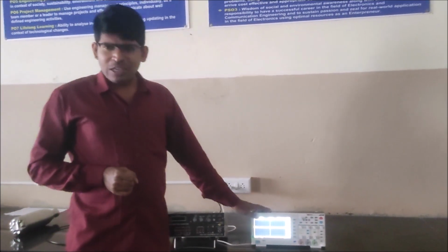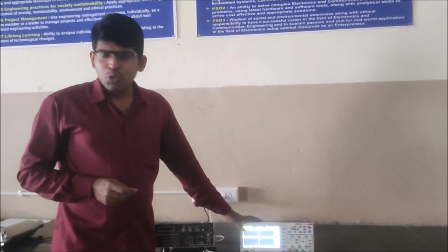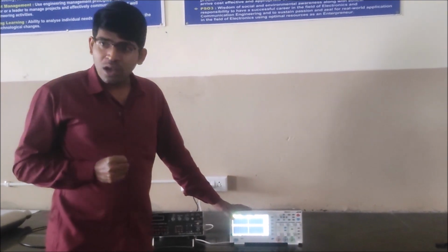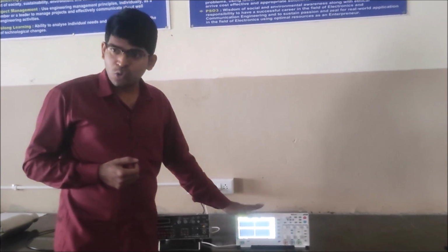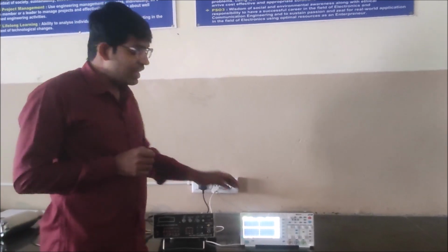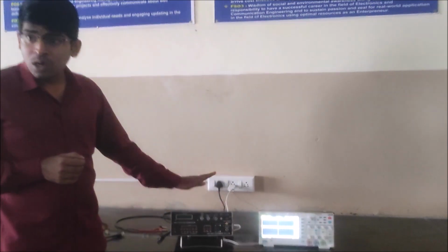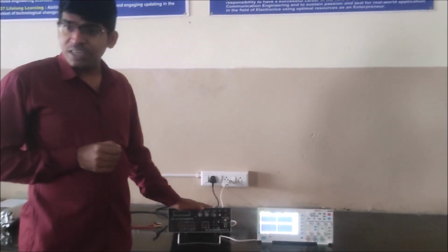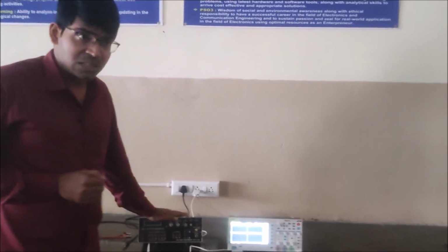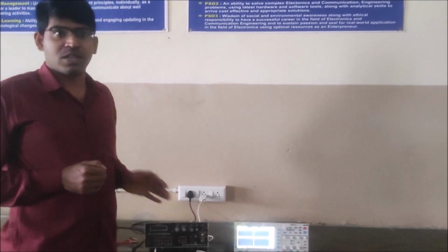In your second year and third year experiments, and also in first year if required in some experiments, you can observe the signal on the CRO. Whenever we want to see the output signal, how the signal is, we use the CRO only. In the CRO we observe the signal and take the readings. So here we are trying to connect one basic signal by using the function generator. This is a 1 MHz function generator, which means the maximum frequency signal we can generate is 1 MHz. From 1 Hz to 1 MHz signals we can generate by using this function generator.